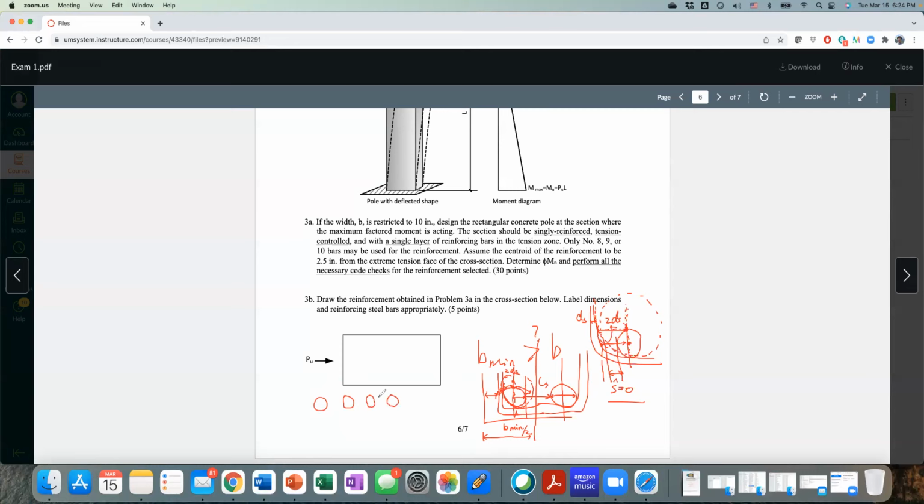All right, let me show you. Do you see it? I'm drawing 5 bars here, right? So first thing you do is you have stirrups going through this way. Okay, let me finish this drawing here. It's going to be a little bit tricky. Give me 1 second. Okay, there you go. So this is what you're talking about, 5 bars, and this is the edge of the concrete. First thing you do is find the centroid, the center line here. Now the problem becomes just needing to calculate half of the width.